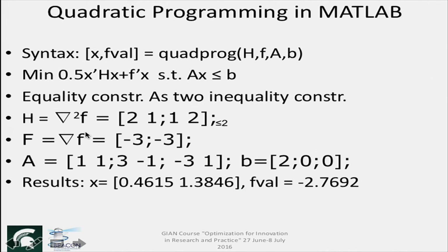Now I'll go to Matlab and quadprog. Again, I'm not going to Matlab and solving it, but this is the program. This is the code. You see, x and fval, quadprog. Now this requires you to give H, f, A, and b. Now what are these H, f, A, and b? Here is the syntax for Matlab.